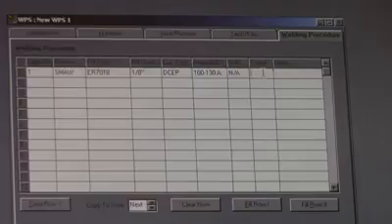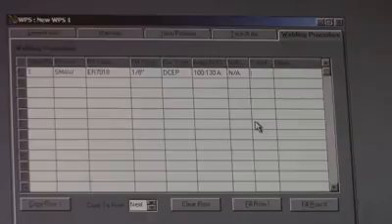Travel speed. The way you calculate this is you get a stopwatch and you lay down a practice bead and then time it and figure out how many inches per minute you're actually doing. With this, it's probably going to be around 8 inches per minute. So I'm going to give them a range again.